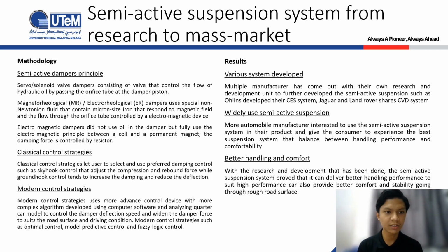So second, the magnetorheological MR and the electrorheological ER dampers use special non-Newtonian fluid that contains micron-sized iron that responds to magnetic field, and the flow through the orifice tube is controlled by an electromagnetic device. Lastly, the electromagnetic dampers do not use any oil in the damper, but fully use the electromagnetic principle between a coil and a permanent magnet. The damping force is controlled by resistor.